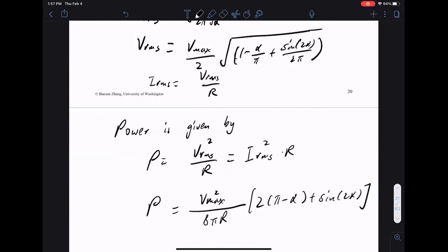So by changing the triggering angle, we can change how much power goes through this SCR. Any questions about SCR? Okay, so SCR will act like a basic building block for us. SCR is our basic building block. That's how we'll construct the other circuits we have in our system.